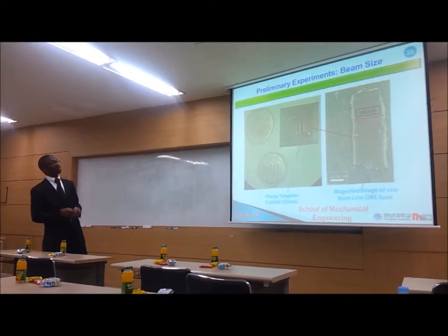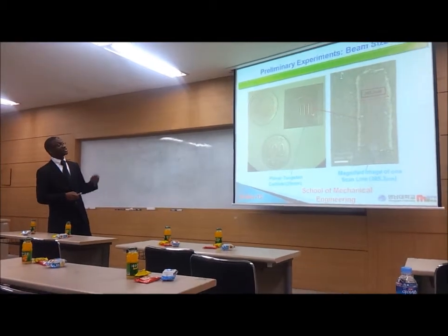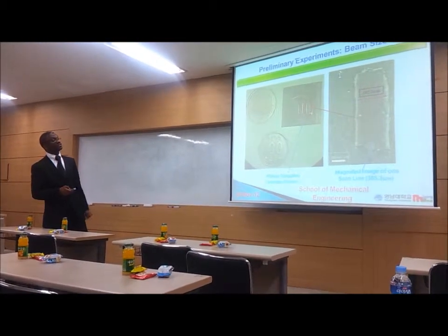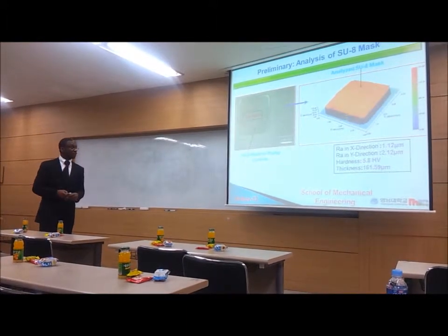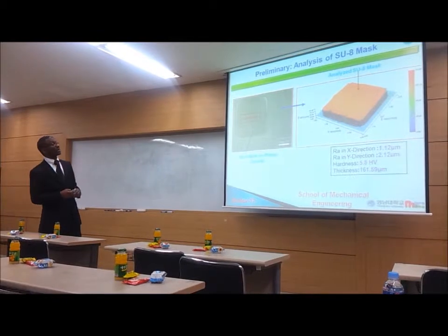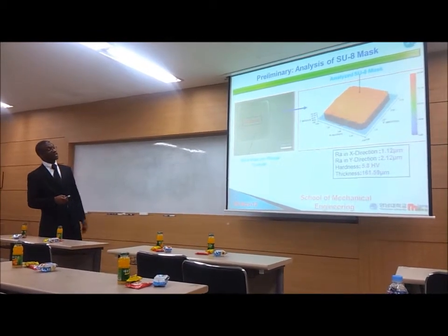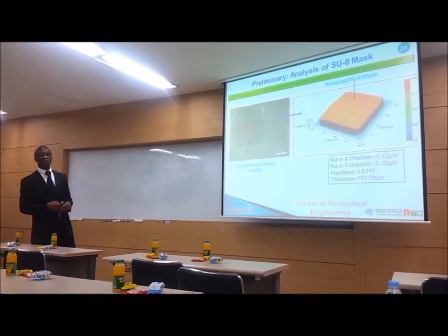Even if we measured by instrument and we find it 324, we had to understand what is the beam size exactly we are having. Then we measured, we found 385.3 micron. Then we had again to scan the mask to know exactly what is the size of the mask we are able to make, and what is the hardness of it, and what is the surface roughness of it.